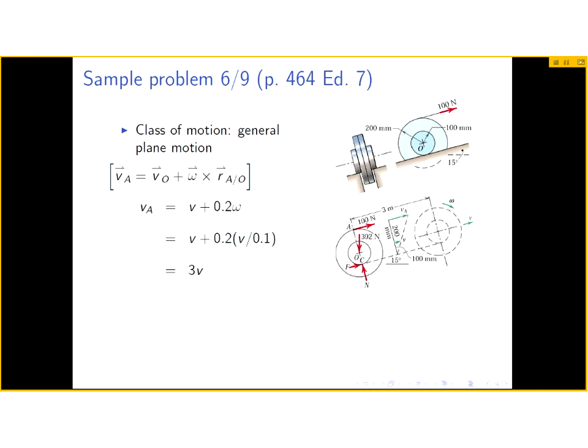But in general, we didn't actually do it in class, so you don't need to use his argument. You can come to the same conclusion based on a relative velocity argument as I've raised here. But he then also comes to the same conclusion, namely that the speed of the cable is 3 times the speed of the center of the wheel, as we've shown here.